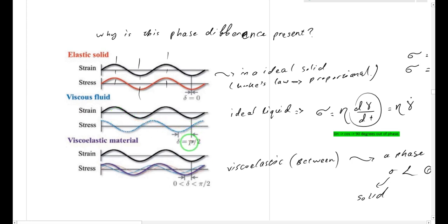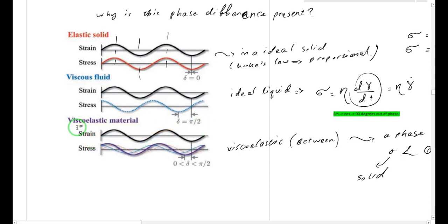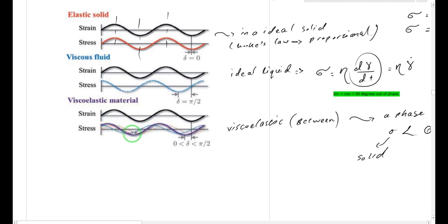So it shows us the phase difference between the stress and strain for the fluids, and it's equal to 90 degrees. However, for the hydrogels, which show the viscoelastic properties, you see here this purple line, that it is something between these two, the phase difference between zero in the case of solids and 90 degrees for the case of viscous fluids.